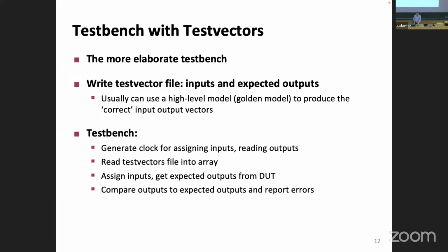Okay. Now, the first thing that we have to realize is everything in a sequential circuit is broken down into these time steps. With the rising clock edge, we start making things available. Then we have some time to do the useful work. Then the output should be available. And then the next rising edge comes so that we can trigger the next set of calculations.